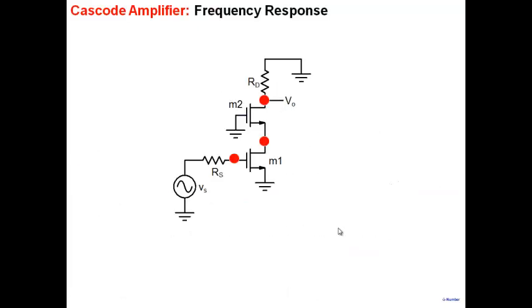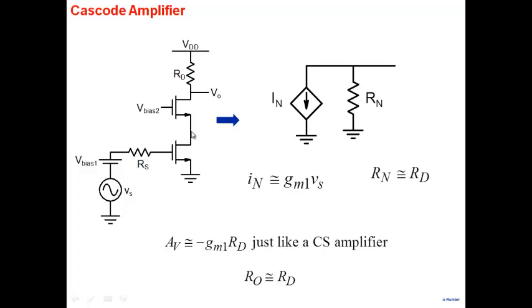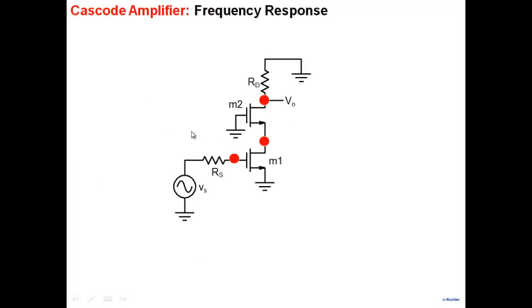All right. As I said, we might be interested in building a gain at this particular point. The reason, as we'll see shortly, is that to calculate frequency response you need to identify all the nodes in the circuit and calculate the time constants at each node. When I calculate the time constant at this node, I have to calculate the net capacitance at this node. One capacitance here is CGD, and this CGD gets multiplied by the gain. What is the gain that I'm talking about? The gain between this node and this node. Therefore, I need a gain between this node and this node also.